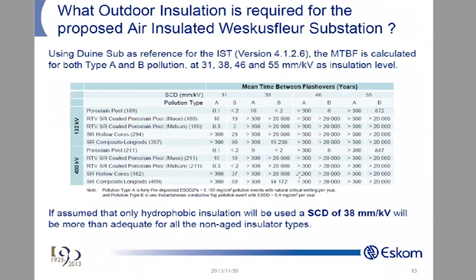Now, I can tell you, which is quite interesting, there's an optimum thickness for the coating as well. Because when you start looking at how this coating works, you've got your porcelain as your base, or your glass as your base. That's a heat sink. The porcelain is a heat sink. So now you put a little blanket over the porcelain. Now the sun is shining, and the energy from the sun is transferred through the silicon slowly into the porcelain, and the porcelain is heating.